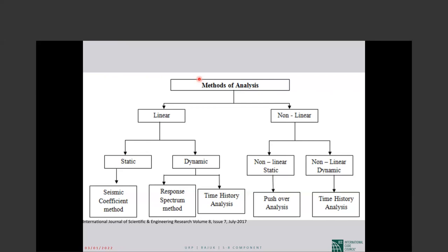The different chapters on different systems say that, for example, if your system is a moment resisting frame, in this beam the bending moment is a deformation control, and all other actions are force control. So axial load is force control. This shear here in this beam is force control. This torsion is force control.